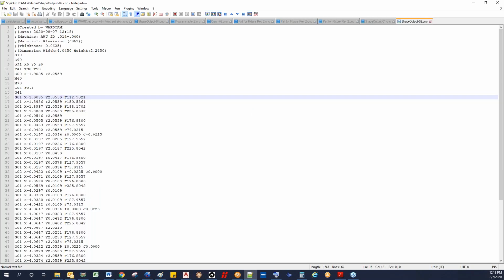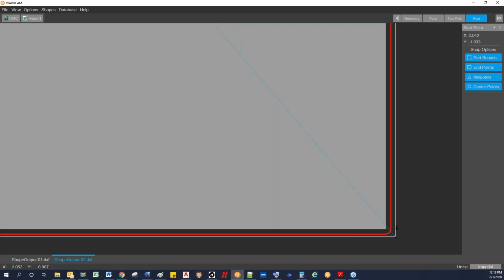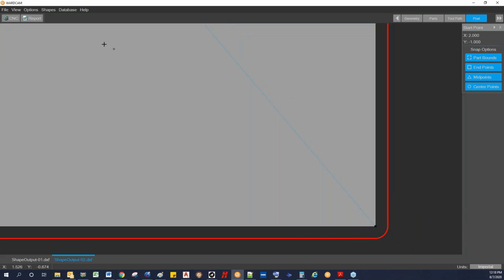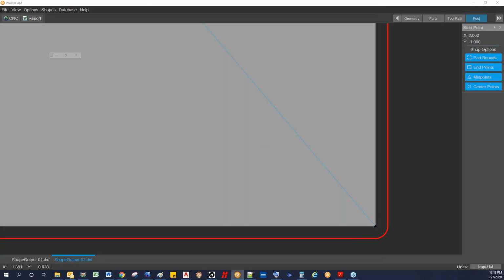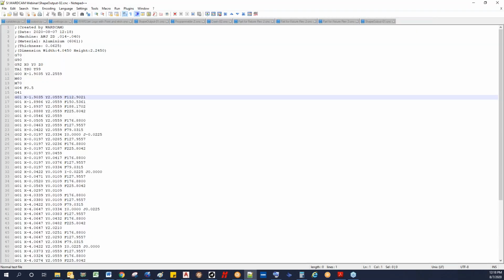And then when this reloads, let me just change my 0 point, because that goes to the perimeter of the part. So we put that right on the corner of the part. We will see now that our offset is half of the 0.45. So those are a couple things that if you change them, you just have to make sure that you either change machine and then go back, or go to that geometry screen and draw something and undo it and then re-add your tool path.